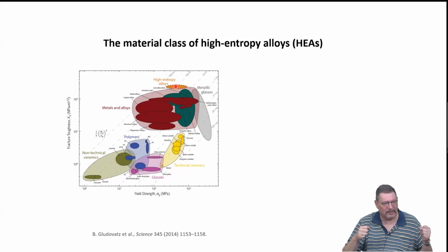Normally when we do a uniaxial tensile test, we talk about ductility. Ductility is related, but often in a complex way, to fracture toughness. But in real service lifetime, fracture toughness is what controls when a critical crack starts to form and open. Once it has formed, it's gone, it's over, goodbye.